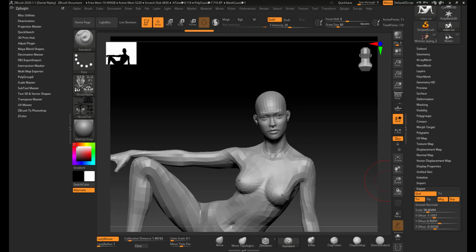Assuming that you've got a good UV map, which is absolutely essential, and assuming that you're ready to do the sculpting part of things, this is where you need to have a workflow for your sculpting. It's a good idea to go into layers and start to store your layers. You don't really want to subdivide your mesh crazy high at this stage.